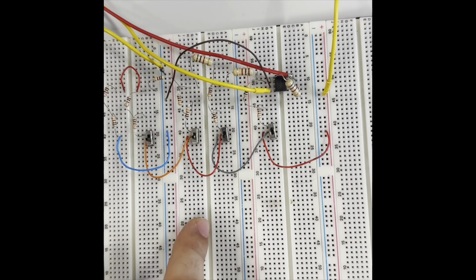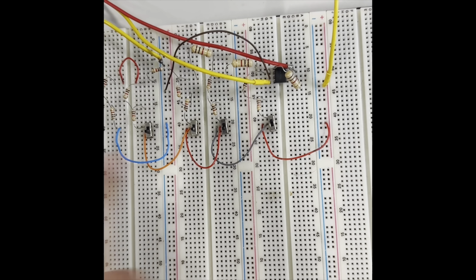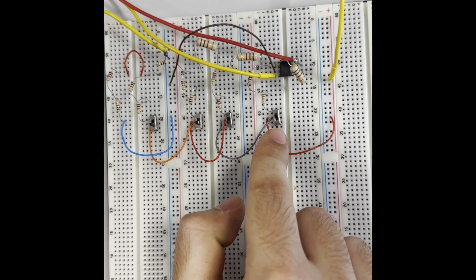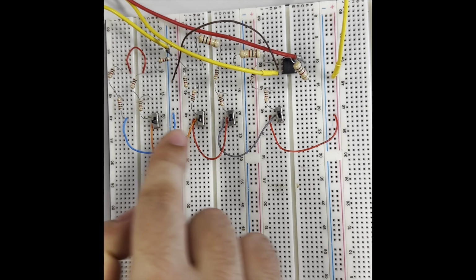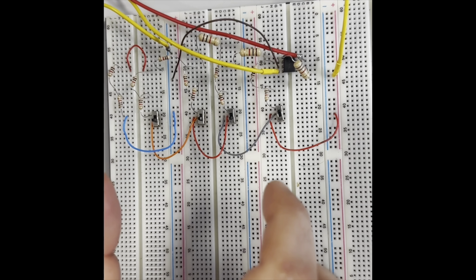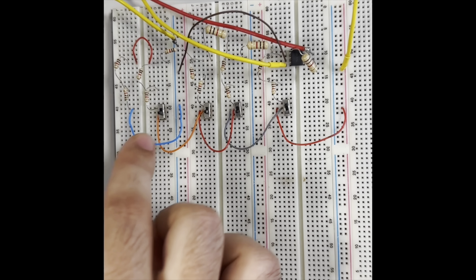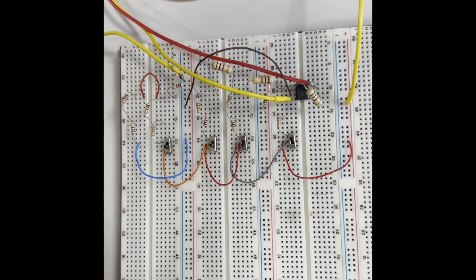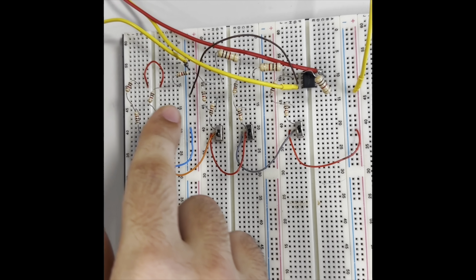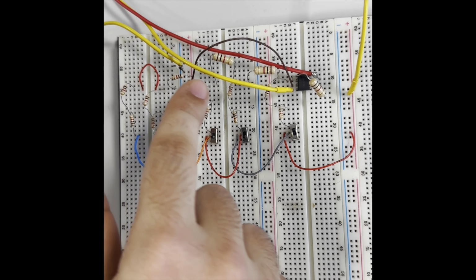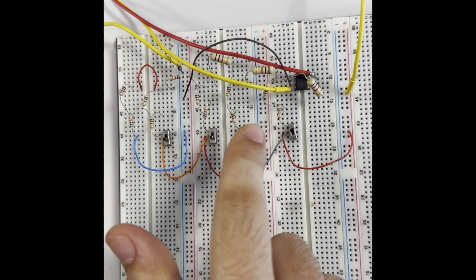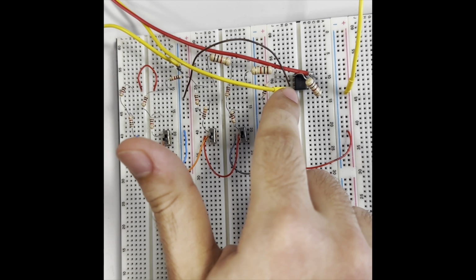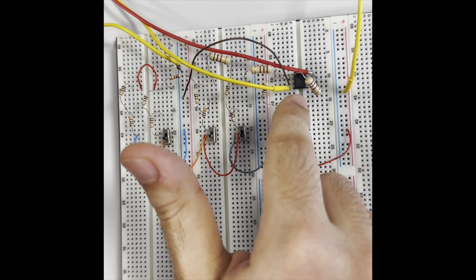For example, if you want to give 1000 to our circuit to obtain an analog signal, we should open our first switch, which is opened right now, and the rest of the three switches should be closed so that we can read a 1000 value from the multimeter, which we will use later. The switches are connected to each other by 1K ohm resistors, as you can see here, and the last 1K ohm resistor is coming from the inverting leg of the op amp to the output leg of our op amp.